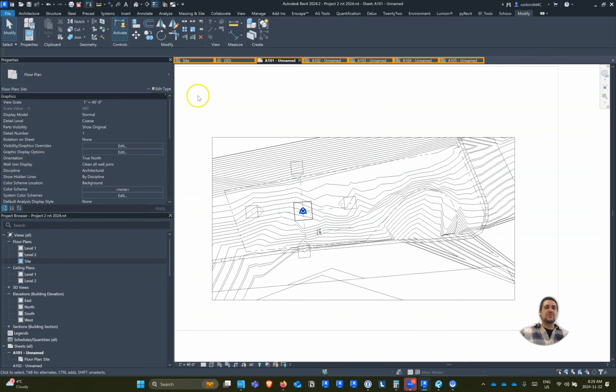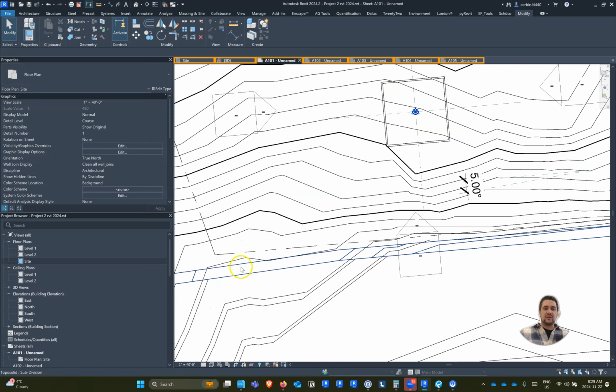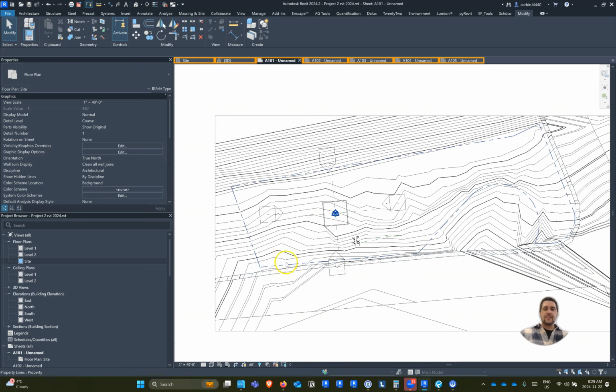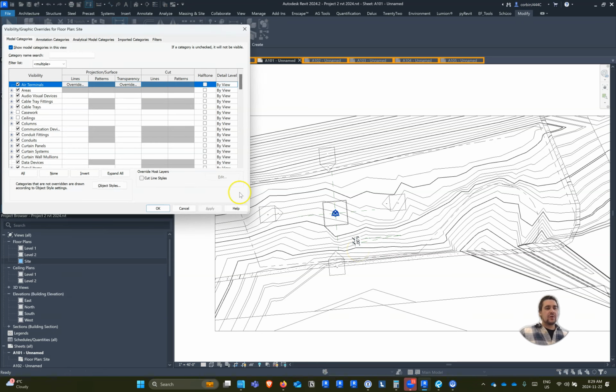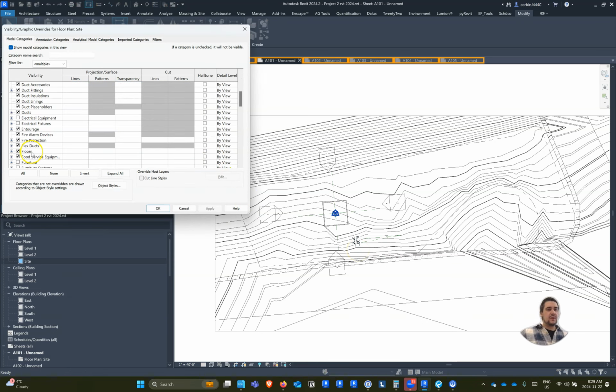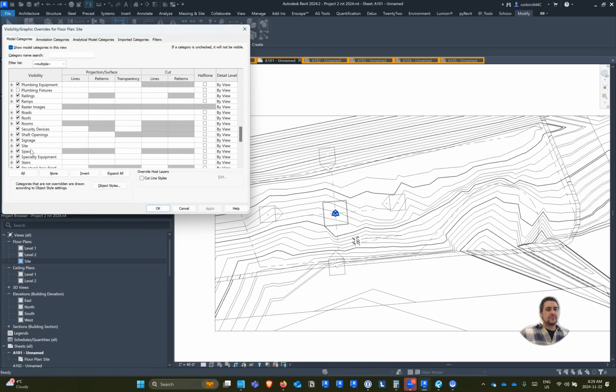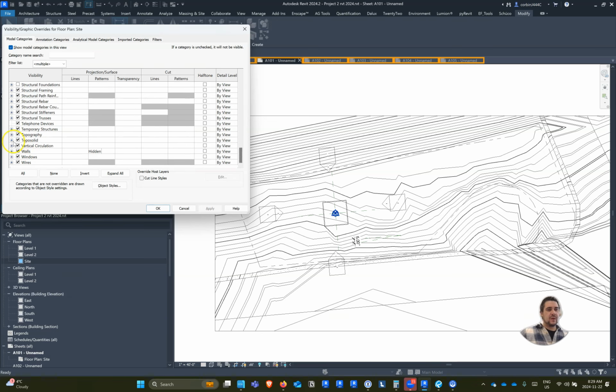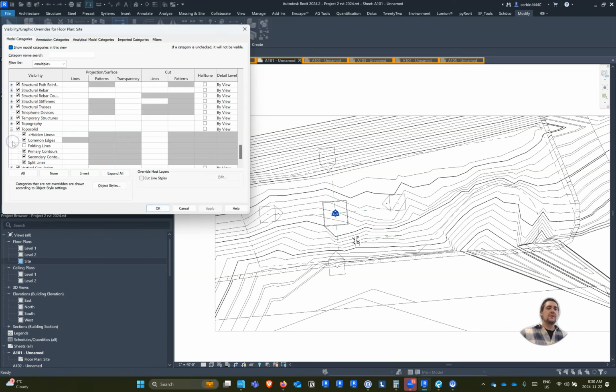And with that, we might want to adjust the graphics a little bit. To adjust the graphics, I like to turn on this line weight button up here at the top, just so I can really see the line weights associated with things. So let's start by going to VG, and we're going to go down here to our topography. In this case, my topo solid. If you're in Revit 2023, it'll be a topo solid, and Revit 2024 would be a topography.